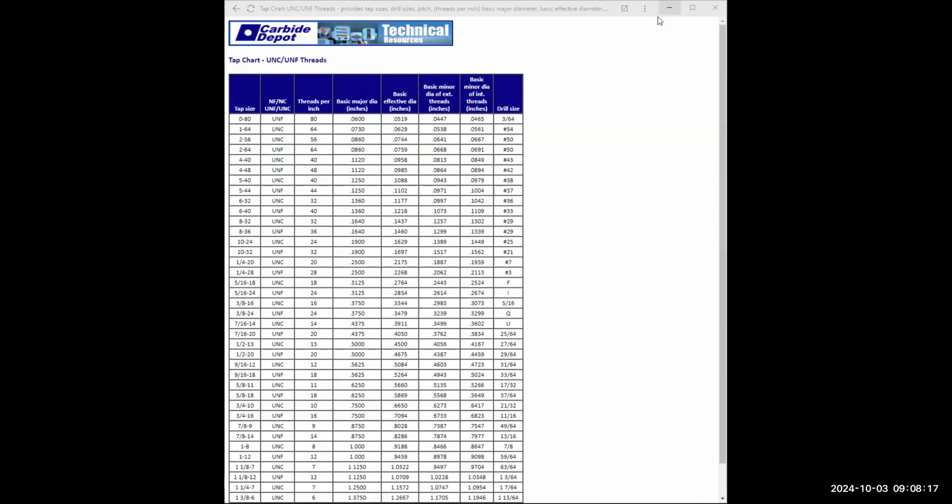I'm going to turn snap angle minus 30 degrees, and I'm going to draw a line from here over this way. Enter. Do you know what that represents by any chance? Any guess? So it's the tip of the drill. That's the tip of the drill.